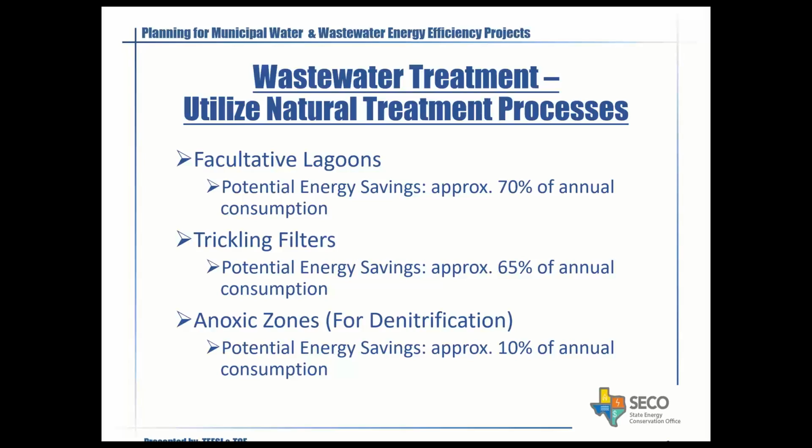And I found out the trick was that they recirculated 100% of the flow back to the primary clarifier. And when they did that, they achieved nitrification and low BOD rates. And that's not in the textbook on a trickling filter. So that is something that I learned in my career. And one of these days, I might have an opportunity to design a trickling filter plant that is very, very efficient.